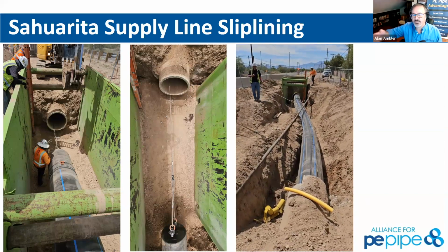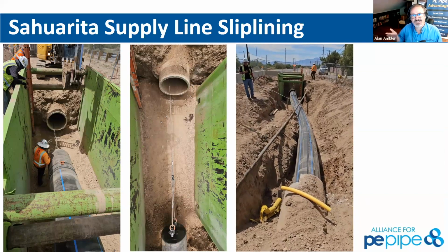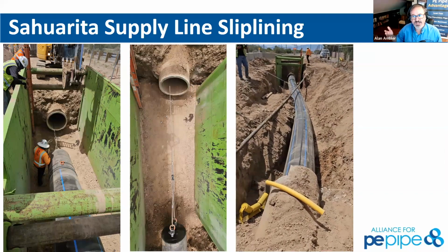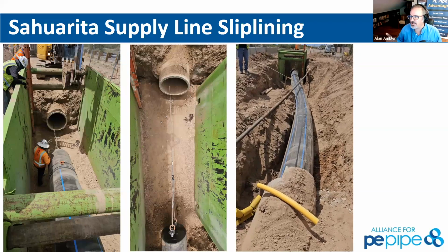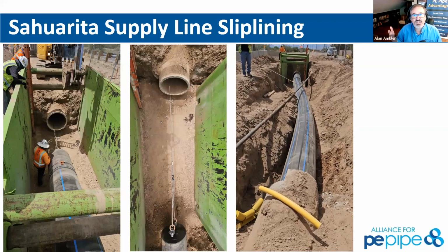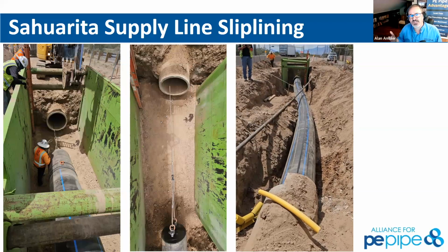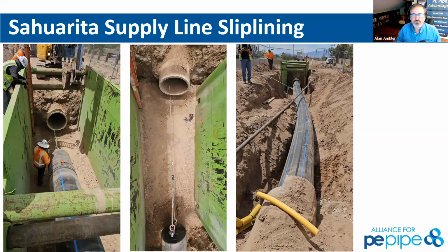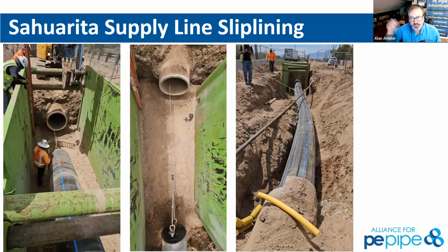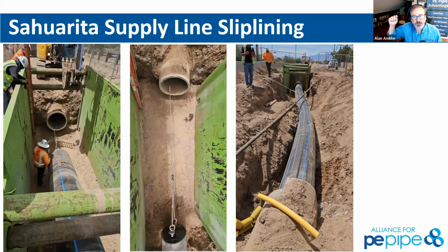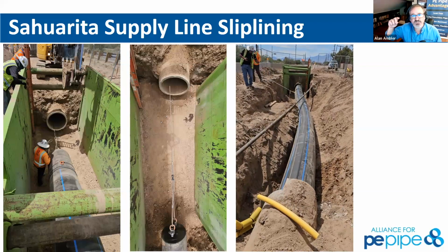We're pulling that through, reinforcing the soil as it gets through there to allow us to make sure we get that HDPE curvature. There's nothing in this video that's going to hurt that pipe beyond its 10% allowable gouge ratio. What that means is 10% of that wall thickness can be gouged, and you still have the full lifespan of the pipe.